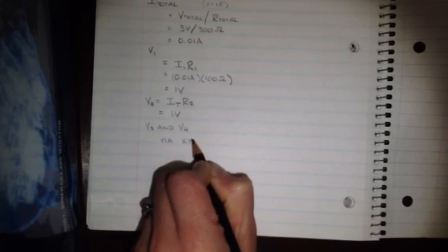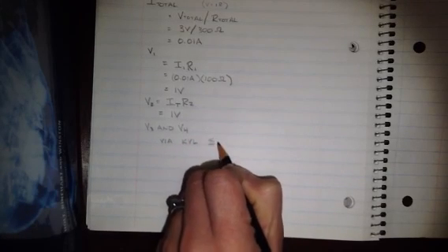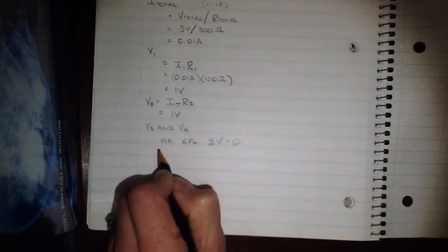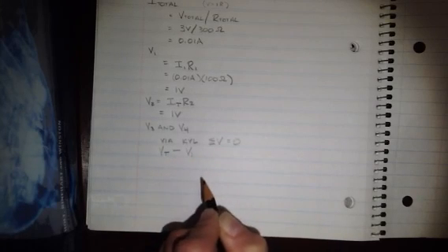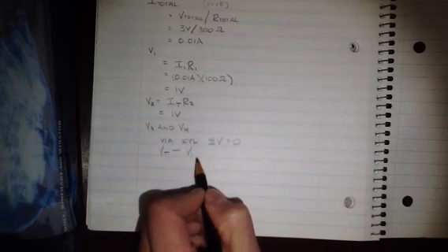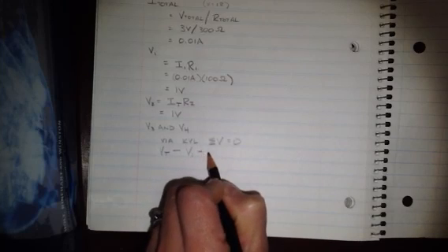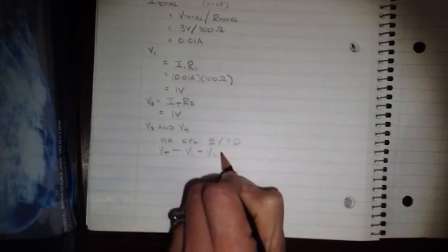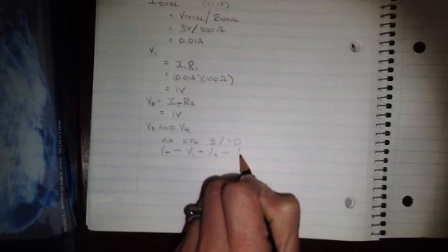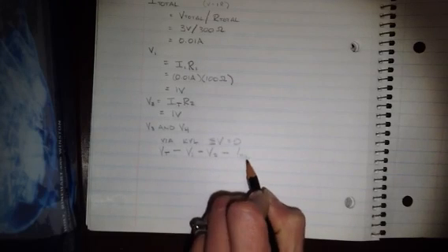Because of Kirchhoff's voltage law, we know that the sum of the voltages is going to be 0. So we have the total voltage put in by the battery minus the voltage removed from the circuit by resistor 1 minus the voltage from resistor 2 minus the voltage from 3 and 4. Because they're in parallel, the voltage drop will be just a single voltage drop.